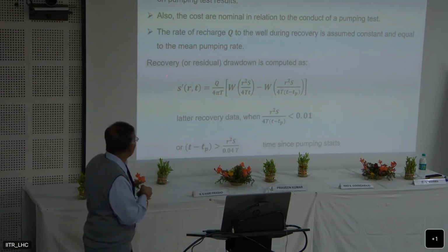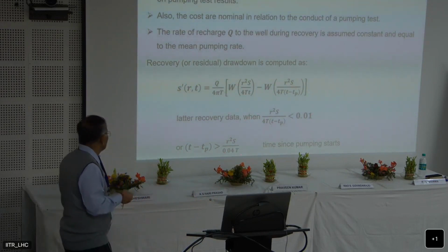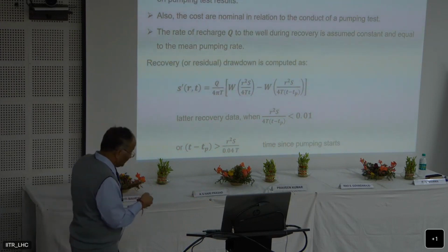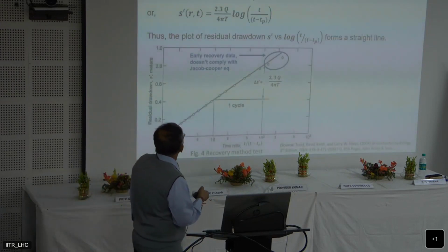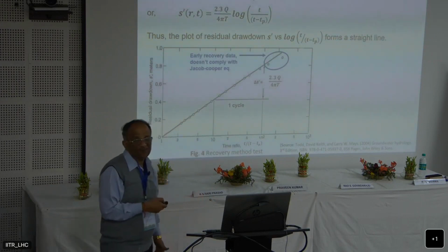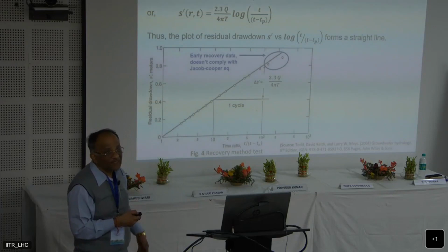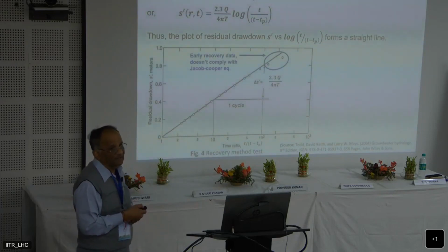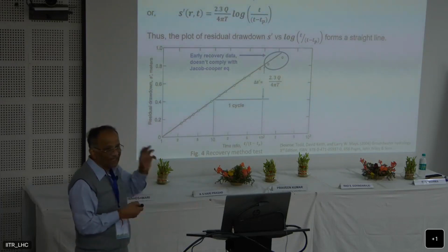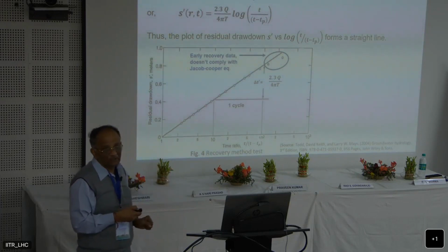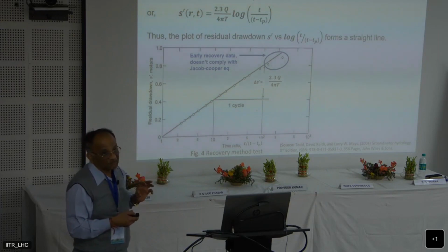This residual drawdown data is a very good test for checking whether the transmissivity we get from the pumping test analysis is correct or not. The recovery really gives you very good information about the transmissivity.